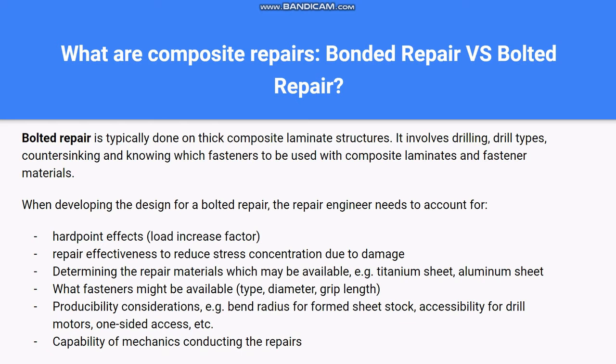When developing the design for a bolted repair, the repair engineer needs to account for, firstly, hard point effects, which is the load increase factor. Next, repair effectiveness to reduce stress concentration due to damage.